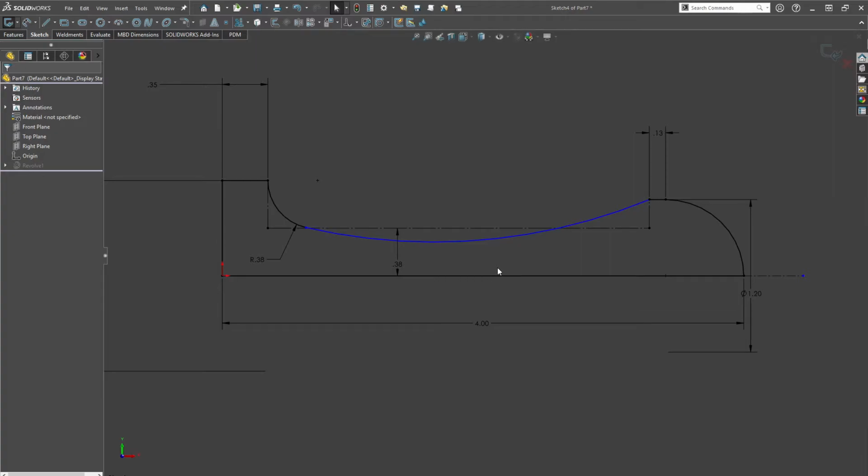Sometimes the only way to fix that circle inversion on itself is to delete it and draw it again, and then it's a new line, and therefore it's a different relation. Sometimes your later parts will break because of that, so just watch out for that. If you can, hit undo and then try to do it again a different way. It is definitely worth not having to redraw lines if you can avoid it, because otherwise it becomes a large pain in the butt.